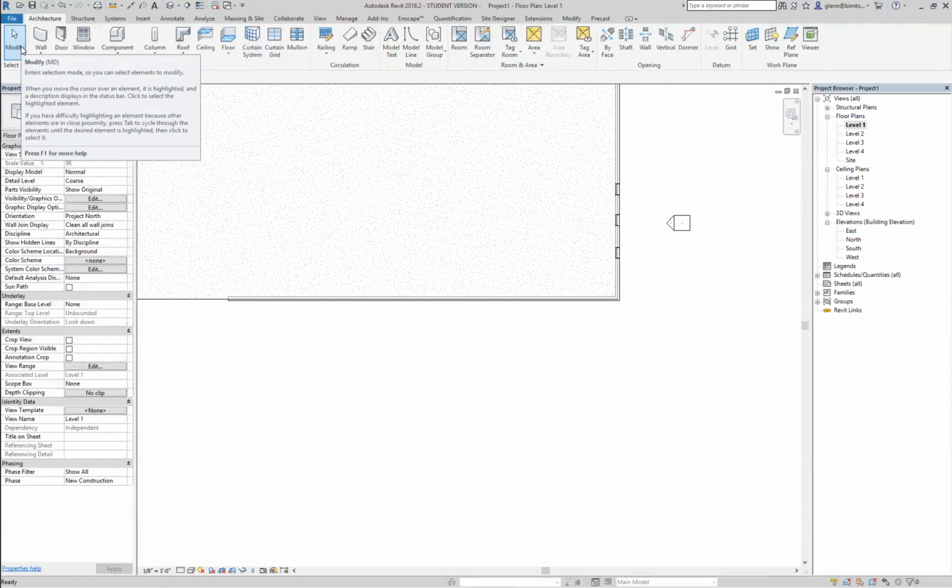You'll find that when we do some 4D simulation and apply a construction schedule, you'll want to make sure that things are broken down the same way they would actually be taken to site and installed on site. Since I do a lot of wood frame construction, we do things floor by floor. I'll build level 1, put a floor in, build level 2, put a floor in, build level 3. But it really just depends.